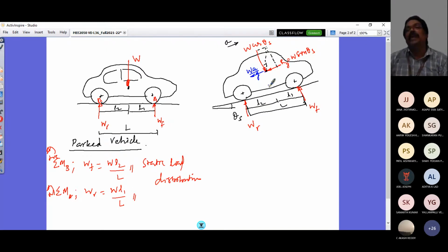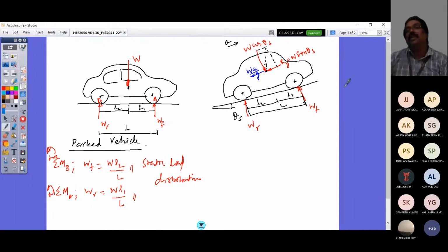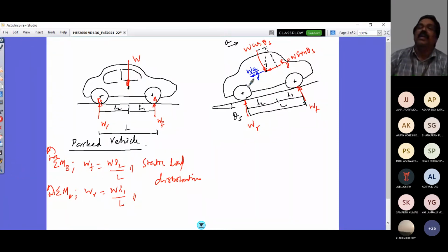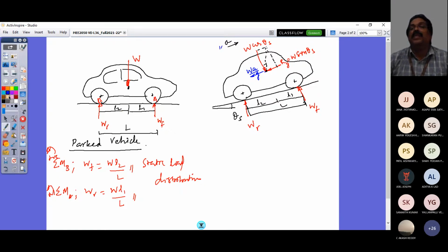If I apply Newton's law, I will not put this diagram here, and instead I would have the rest of that, and that's what is equal to a car with only the force W A by G at the CG location in a forward direction, right? That's what you know, and this is your dynamic equilibrium, and I have this D'Alembert force now acting at the CG location in this direction because of this acceleration. And in addition to that, there are various resistance forces that are acting.